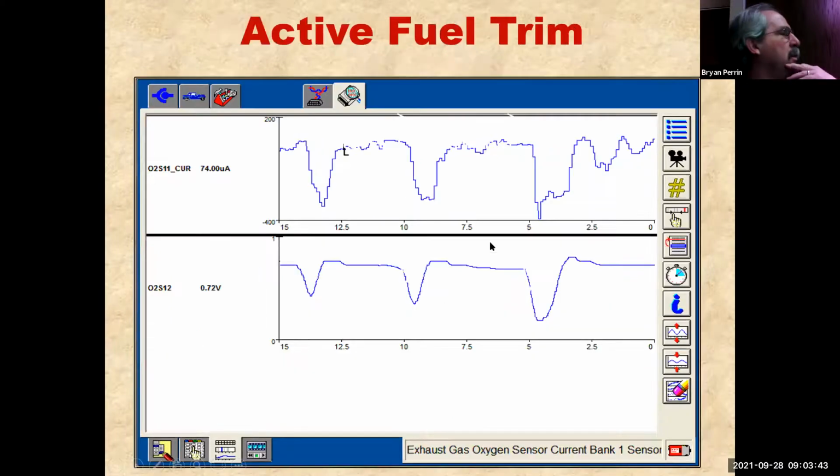So if I look here, here is my front air fuel ratio sensor. And here is my rear O2 sensor. Remember, air fuel ratio sensors read a high signal when they're lean, a low signal when they're rich. So if I look right here, we can see that my rear sensor is high, it comes on, and then it drops, and it drops right here. But when it drops low, saying I'm lean, what does the front sensor do? It goes from lean to rich.